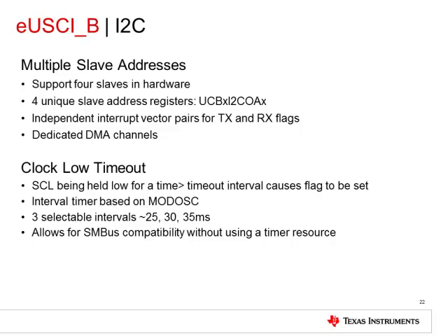When one of the slave registers matches the 7 or 10-bit address seen on the bus, the address is acknowledged. Following this, the corresponding receive or transmit flag that matches the received address is updated. The state change interrupt flags are independent of the address comparison result. They are updated according to the bus condition.